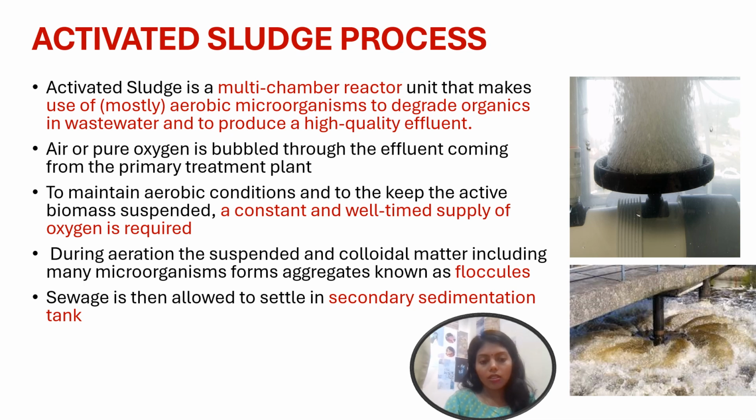Diffusers, which you can see on the right side of the picture. These are all the diffusers. Like this, diffusers will supply oxygen as very fine particles of air, or we can use another way, that is the mechanical aeration process. In this process, sewage droplets will fly due to high turbulence. They disperse in the air and come in contact with the atmospheric oxygen, thereby the aerobic bacteria get oxygen for decomposition.